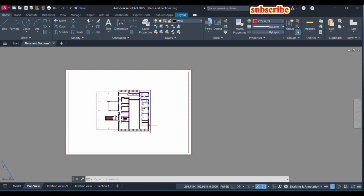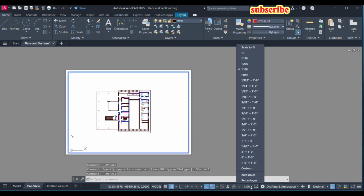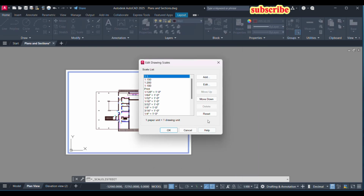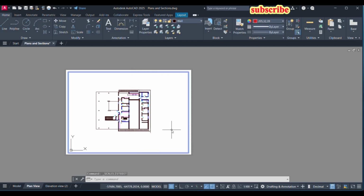It looks like it is a bit small, so we want to have maybe 1/75, and therefore we can click on this scale and create a custom scale. So here we can add a new scale of 1/75, for example, and it means that one paper unit equals 75 drawing units. Okay, we click on OK and click again on OK.